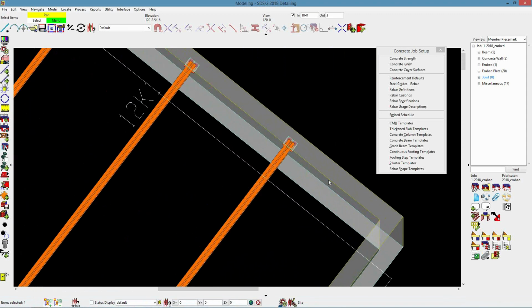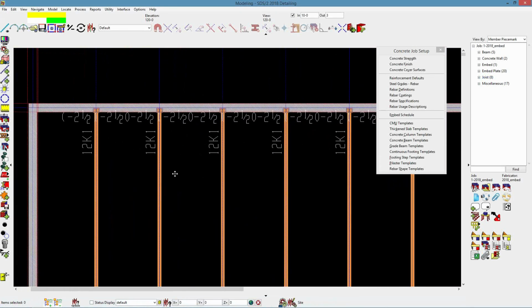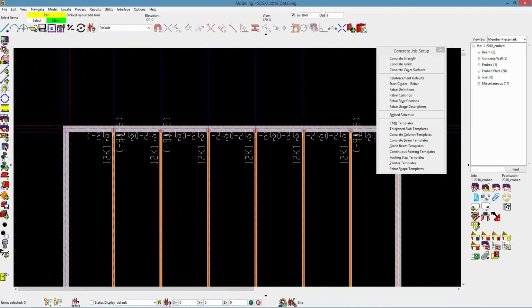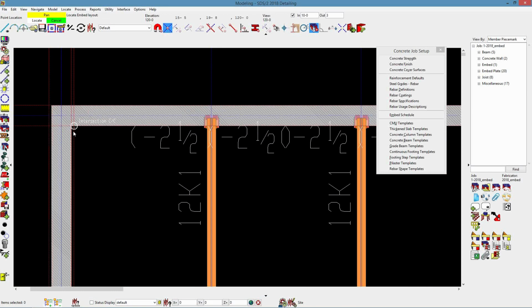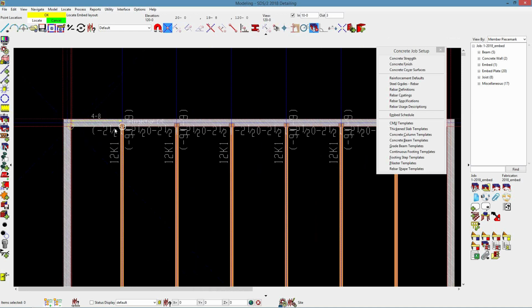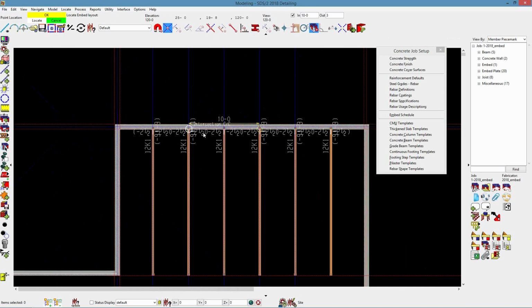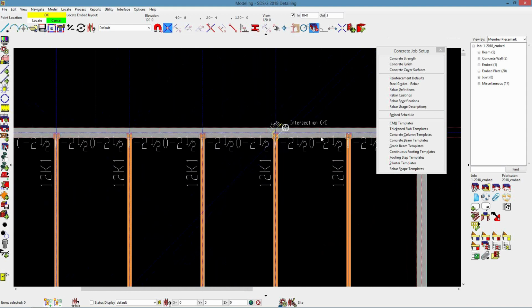Now if we wanted to put in some angle to act as a support along with our joist for some decking, we can use the Embed Layout Add tool, and we can add it all along these points here. So I'm going to select the left end of the angle and then the exact points of all of these joists. Okay. Now each point that I'm picking here